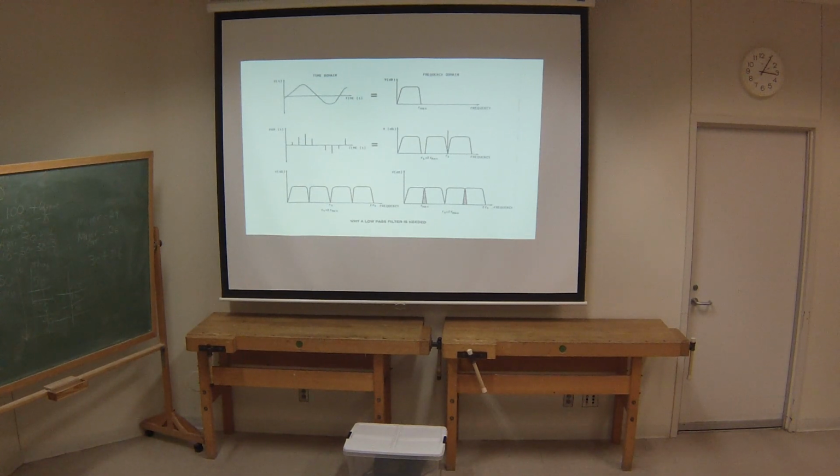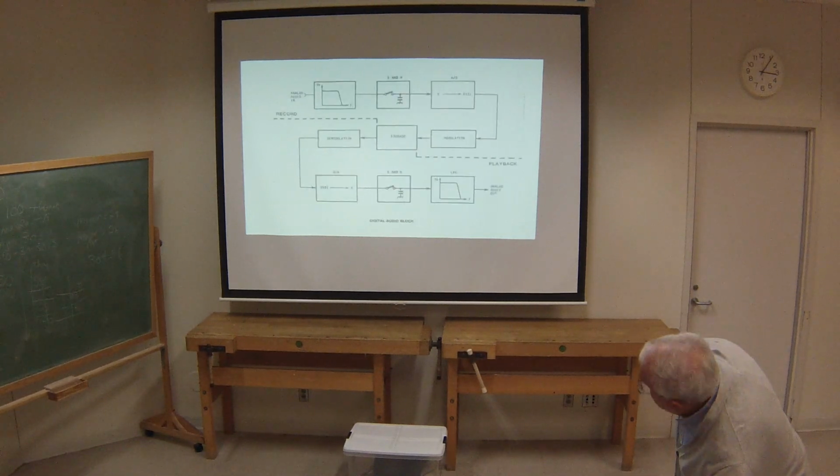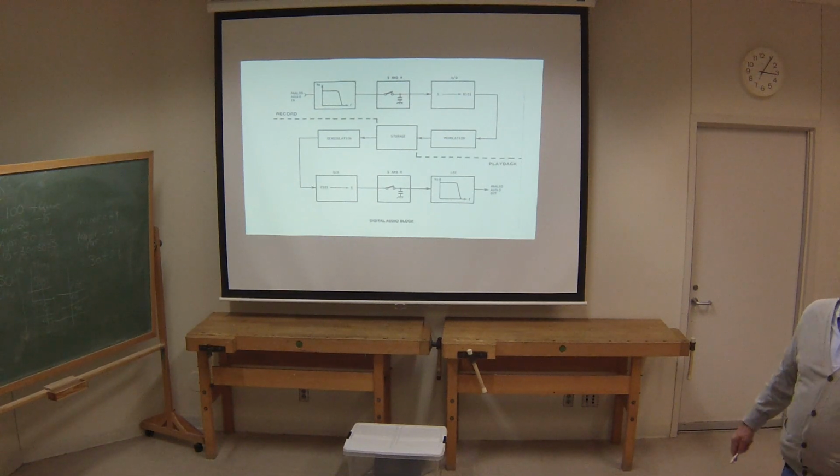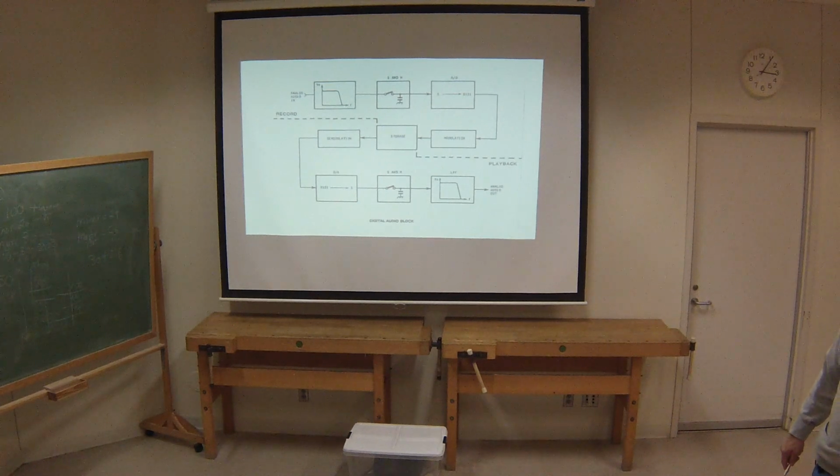Would be very, very bad, low frequency distortion. So anyway, the idea is you really want to have some fudge room here. Otherwise, your low-pass filter, remember we showed in the previous slide, the output is a low-pass filter, right here. That low-pass filter has got to be so sharp that it'd be very expensive and difficult to build.